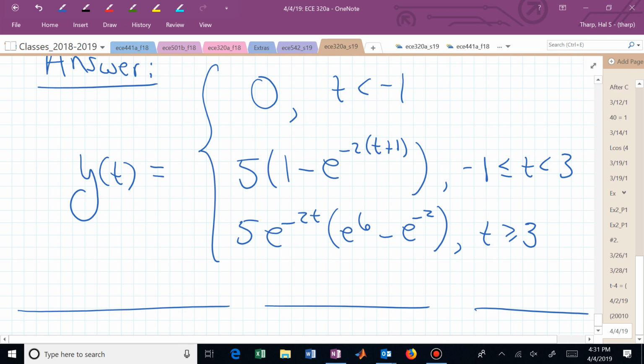They turned it off. Then what do we do? We're an RC circuit. We discharge. And how do we discharge? Exponentially. And what's our time constant? That hasn't changed, has it? It's 1/2. How many time constants do we have to wait until we... 5 time constants, which is 5 times 1/2, that's 2.5 seconds. So when can we quit watching this exciting shape?